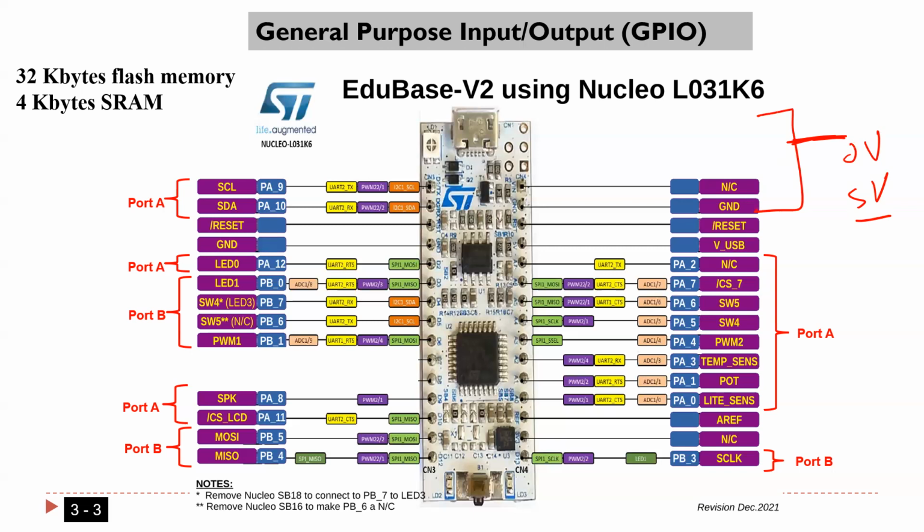You should know how to do that, okay? Also, I explained if you have an input pin, in this case, there should be some external circuit here, for example, which I'm going to explain for sure. The external circuit should put here 0 volt or 5 volt. And the microcontroller should be able to read, to know if this pin is 0 volt or 5 volt, okay?